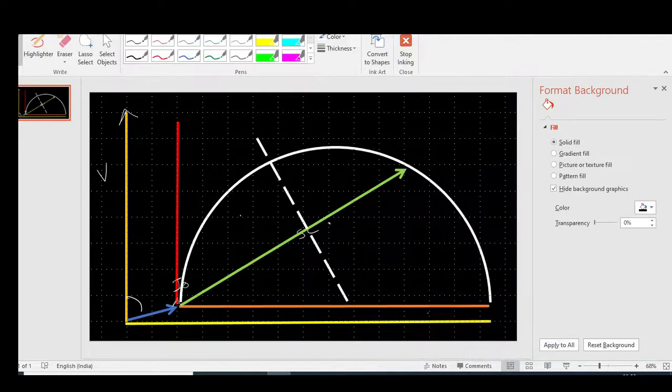Yes, now this diagram is scaled, and let me quickly repeat how we did it. First we draw V, that is a vertical line. Then from this V we measure theta naught. Then we draw I naught. All this drawing was done to scale. Then a line parallel to the horizontal is drawn from the tip of I naught.